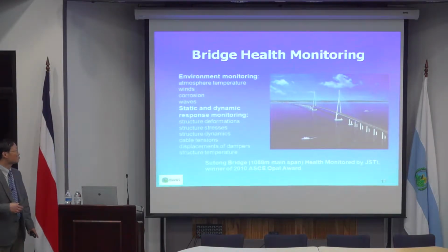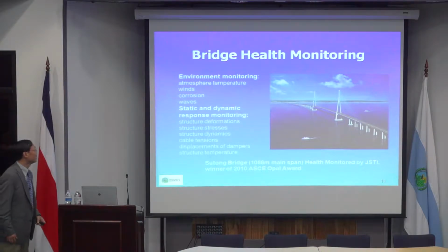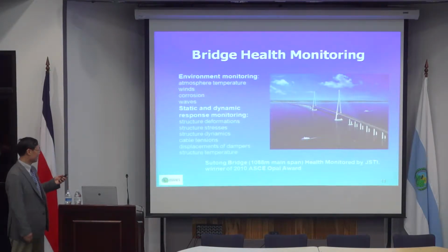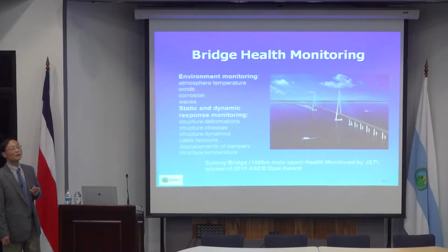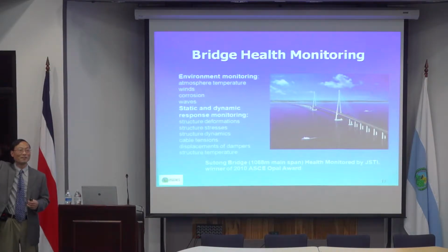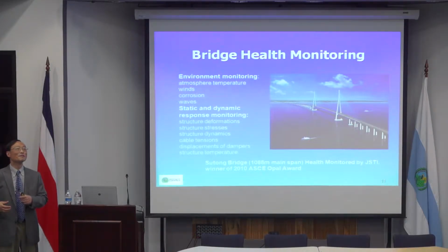I'll tell you why. Basically, that's the concept, just so that the system can tell something is wrong, so we can go to see it. And so there are sensors. The sensors typically have to be installed when the bridge is built. If you install sensors after the bridge is built, it will look ugly. You will have a lot of different sensors put on the bridge, people will look at them, and they will also be damaged easily. So these sensors have to be designed during the design phase and constructed during construction.